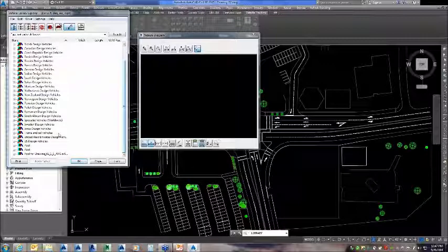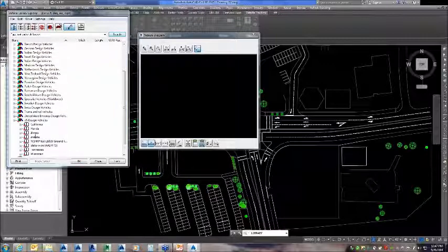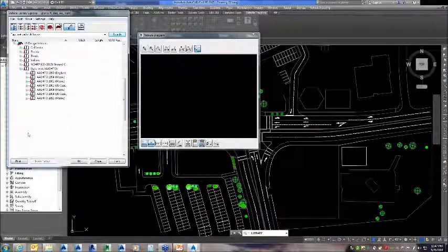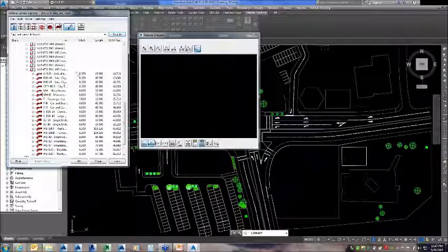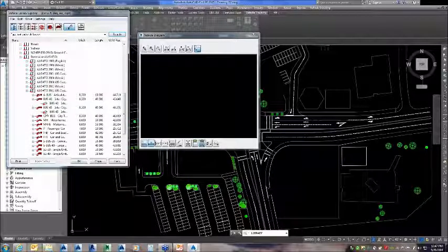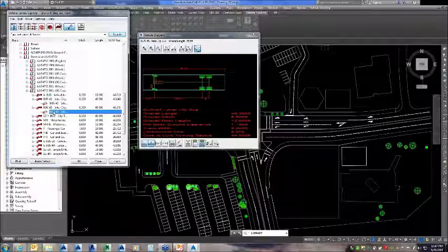If we zoom down, if we went to U.S. design vehicles, you can see we have specific states. And then we also have, if I scroll down a little bit further, statewide AASHTO. So if I went to statewide AASHTO, I can use custom or metric, so U.S. custom based upon vehicles. And there's, again, over 1,800 vehicles that we can utilize. So specifically, if I just wanted to do a city bus, it's going to give me a diagram of a city bus, an overall length, width, body height, minimum body ground clearance, lock-to-lock wheel time, and curb-to-curb turning radius.